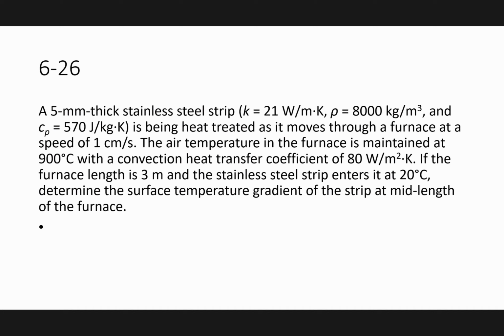Does anyone want to suggest? We have to start with the Biot number. Okay, I calculate the Biot number. What should I do with the Biot number? Well, we determine if it's a lumped system or not, and then using the speed, we find how long it takes to get to the middle of the furnace.